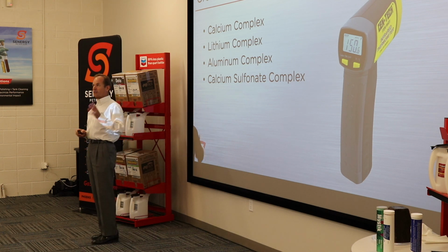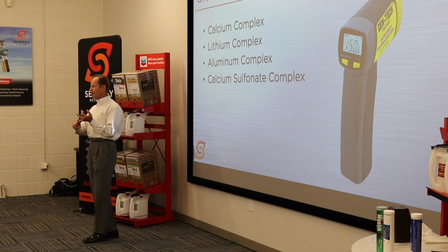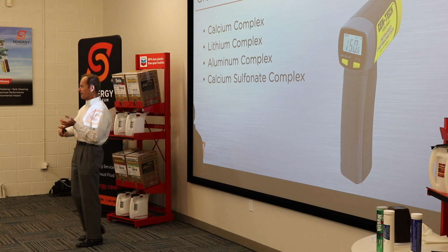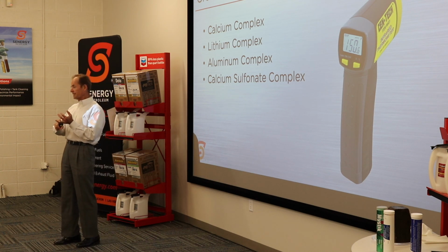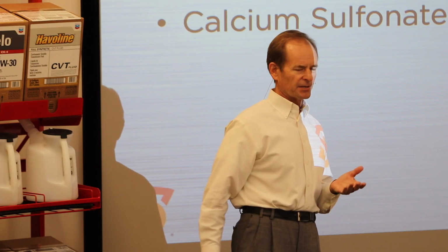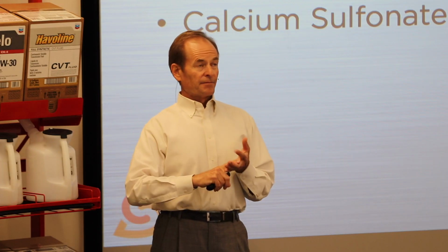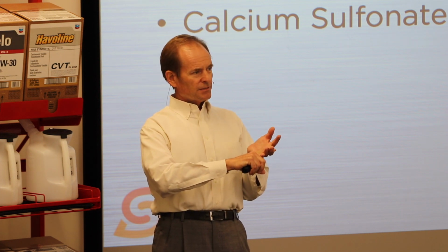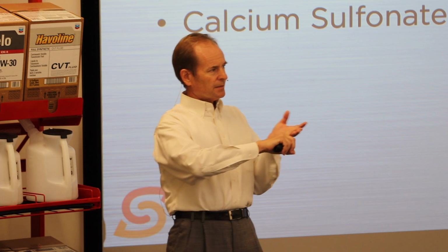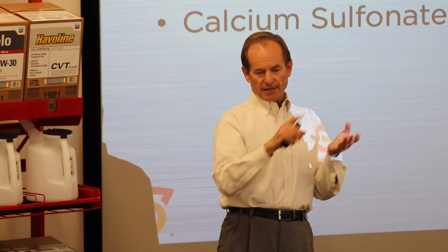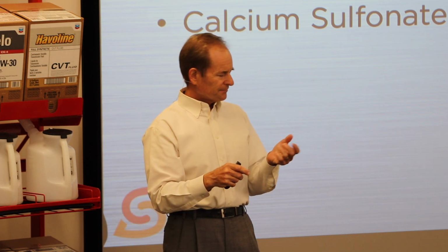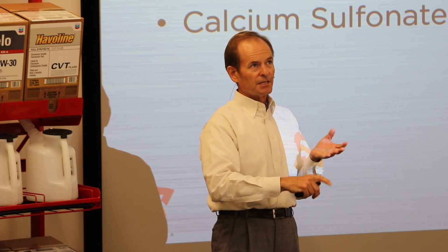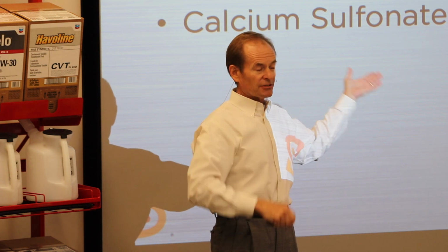The calcium sulfonate complex greases have tremendous water resistance. Really outdo anything, even without any additives for it. They got great high temperature performance, at least as high as, if not higher than, anything out there, lithium complex. If you remember, we talked 2 minutes ago about EP additives, and the EP additives were these sulfur phos additives. Well, this grease is a calcium sulfonate.